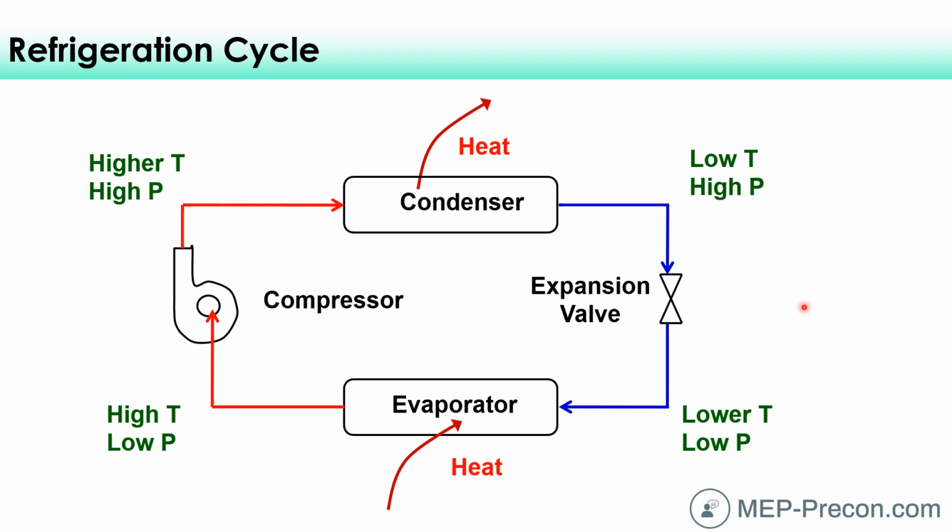You could produce a refrigerant cycle with just a bunch of aerosol cans. You could put a board across the top of the nozzles and just push down on them all and blow some air between the cans. That could be your heat exchanger. As you do that, you're going to lower the temperature of the cans, and as the air flows across them, you put a fan across the cans, there's going to be heat transfer that takes place. The cold cans are going to remove the heat from the air, and you've produced air conditioning that way. You've removed the heat from the air. You've cooled down the air.